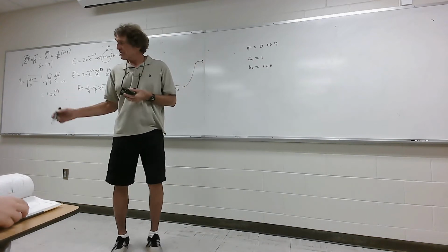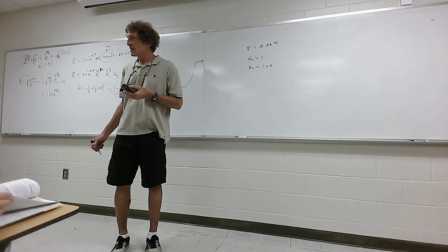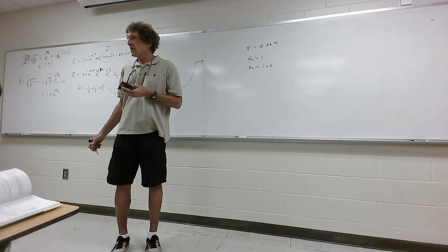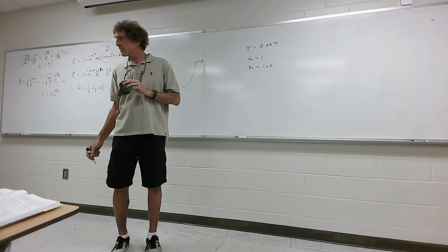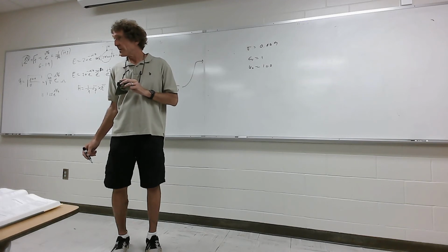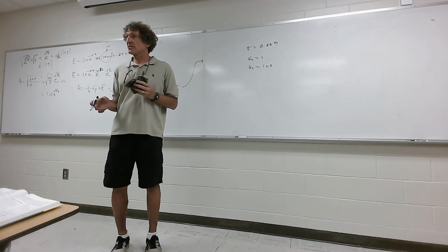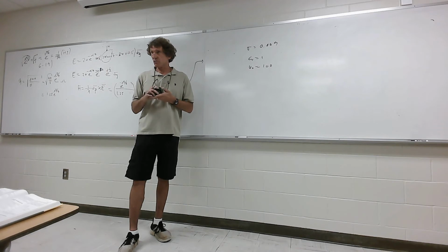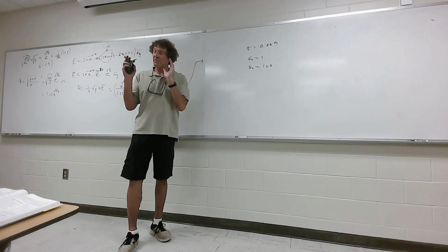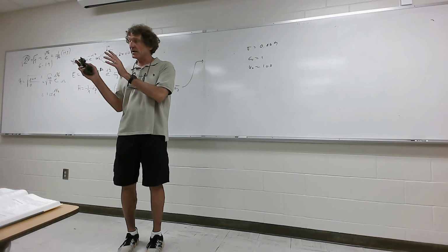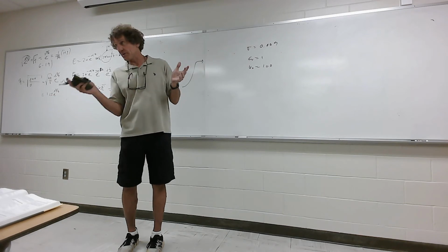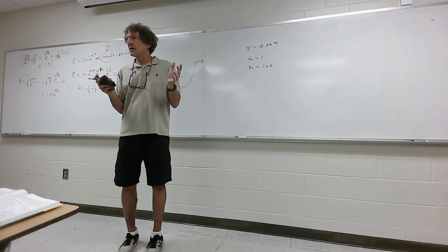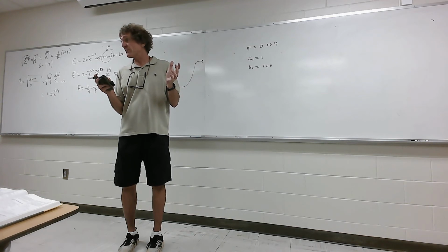All right, so what does it ask now? It says to define the instantaneous form of the electric field, but I was just curious about what type of material. All right, by the way, with this information, just take a look at it. Do they give you a frequency? They give you a 1 millimeter amplitude magnetic field and 100 megahertz. Now, knowing 100 megahertz, right away you can figure out the value of omega times epsilon, right? And compare that to sigma. Y'all follow me? You can find out if it's a good conductor or not. And once you know if it is a good conductor, and I'm not sure it is, then you can go ahead and get the rest of the information straightforward.